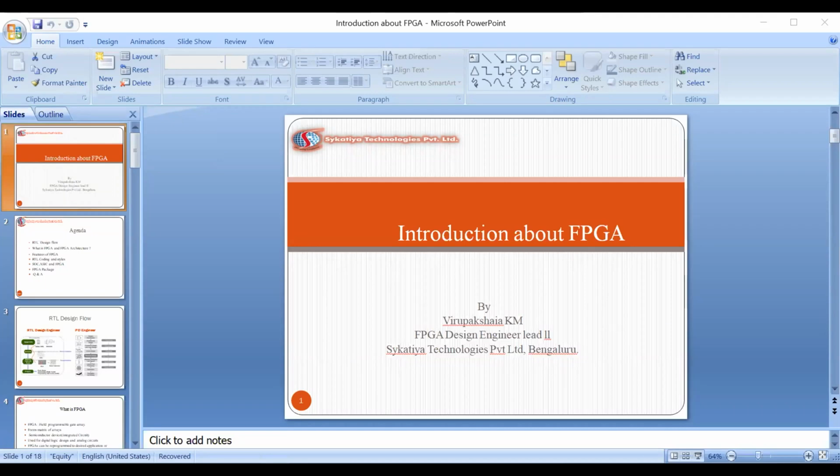Verification as well as validations and physical design engineers. So they will also do some of the design flow. So for any codes or any designs and any projects, these are the steps to be considered for your design. Okay. So if you miss your synthesizing, you cannot go for the programming of the design. Okay. First, once you've done the design, you have to do the synthesizing. Once you've done the synthesizing, you try to do the mapping and place and routing with the optimization of your design. Then you go to the programming.